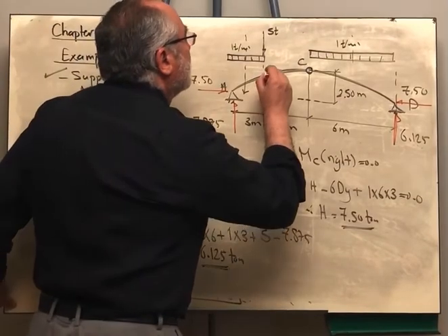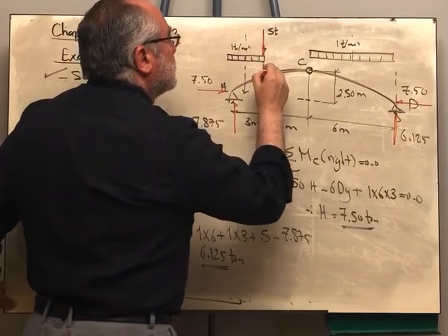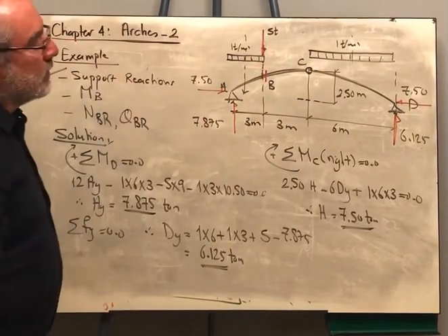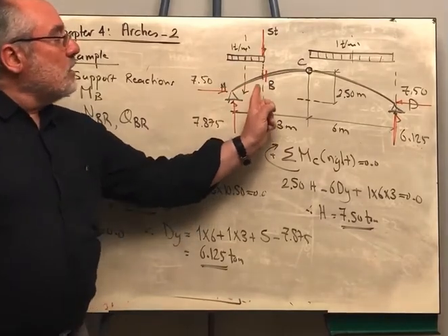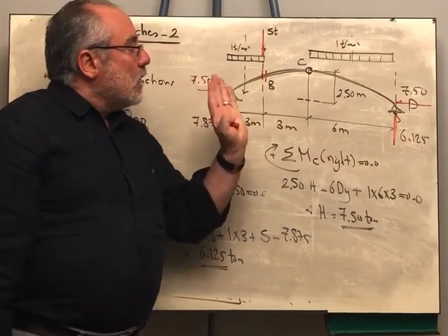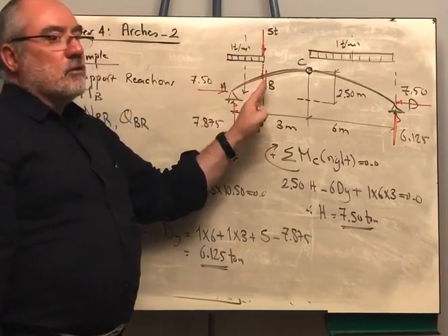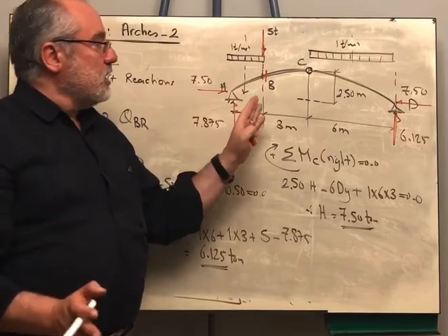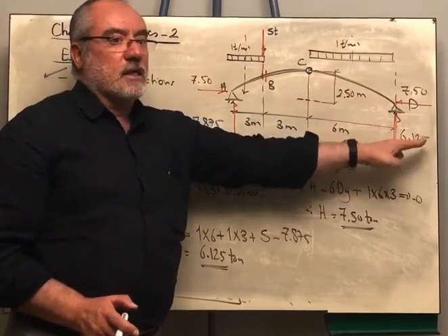Right of B, what does that mean? It means at this section, right of the concentrated load. Okay. Not necessarily, because he said right of B, that I should take the right portion of the arch. Now I knew from this question that the section is right of point B, but I have the freedom either to take the left hand side or to take the right hand side.